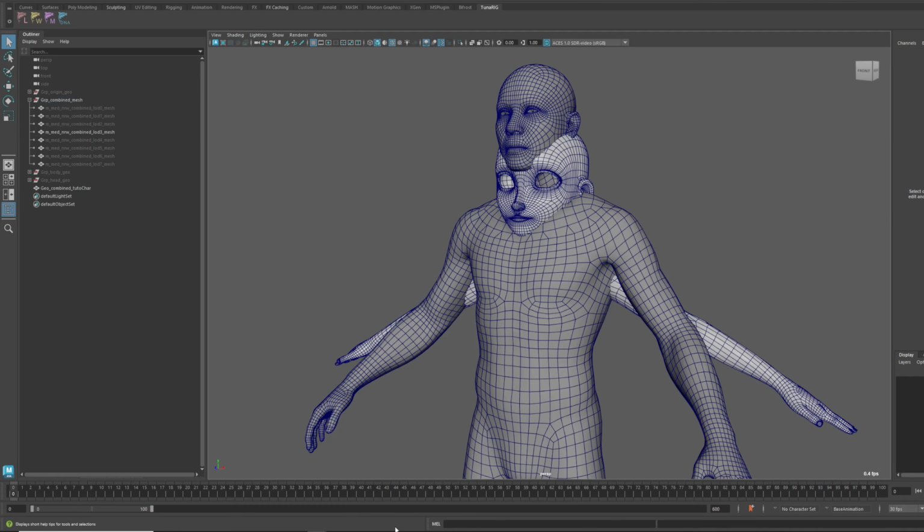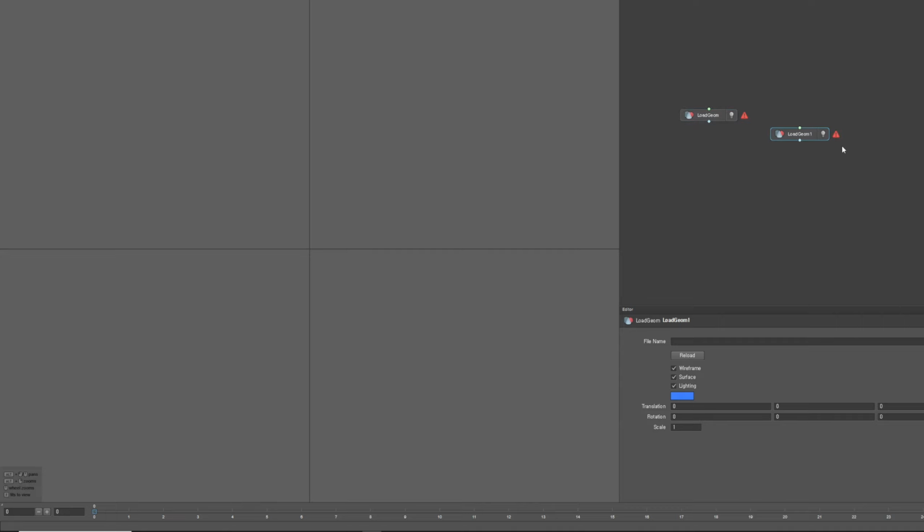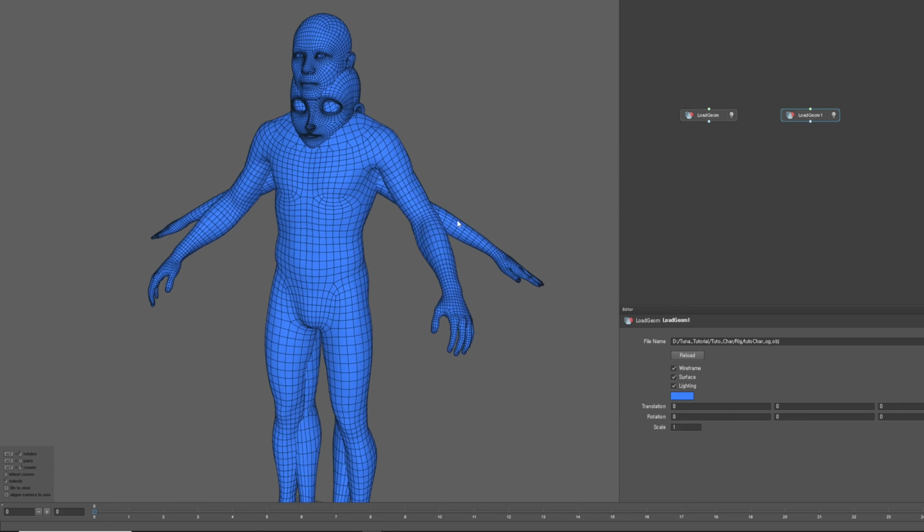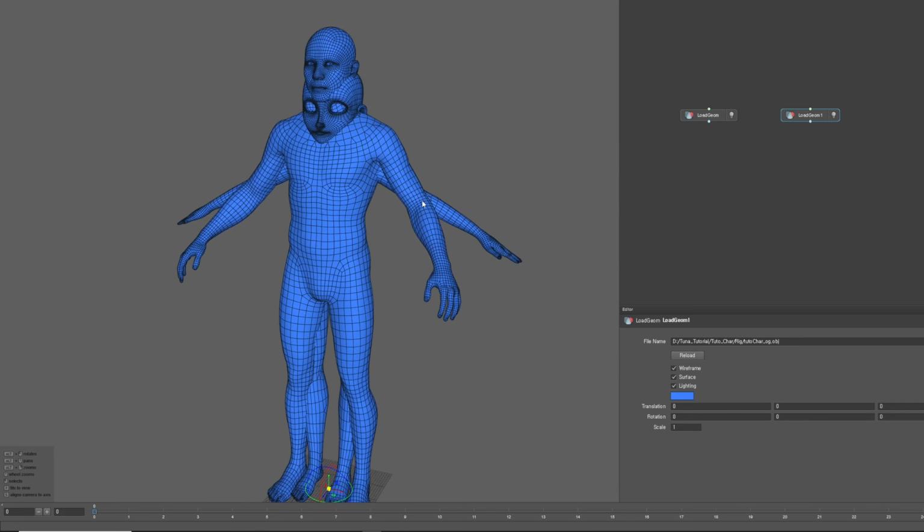All right, let's move on to Wrap 3D. Here, we will import two geometries. Please import the MetaHuman LOD3 mesh that we exported earlier, along with the original character mesh. Now, let's load some nodes needed for the wrapping process.